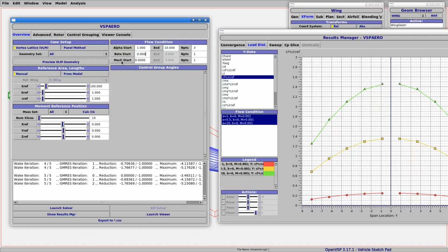There's also Mach start, which is the airflow speed, so you could set that to Mach 1 if you were making a different kind of plane. I actually tried this at 0.1, which I think equates to about 120 kilometers an hour, but I didn't really notice any difference, so I never bothered with it again. I just leave it at 0. So anyway, that's why we have 3.